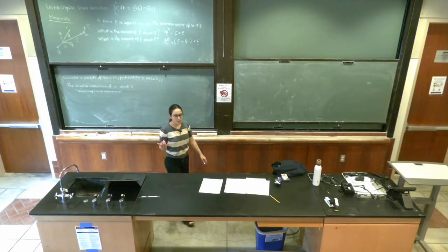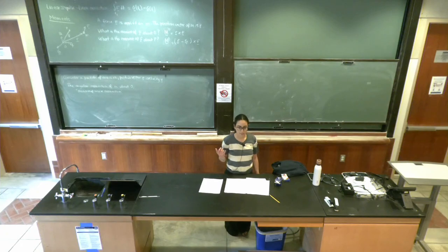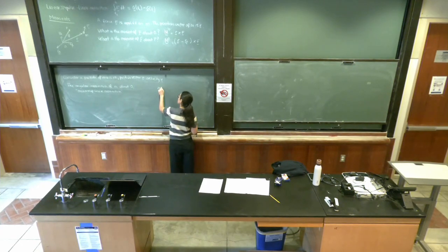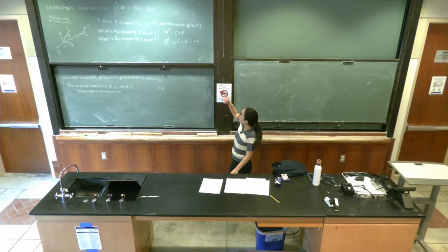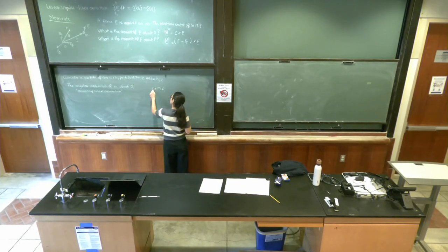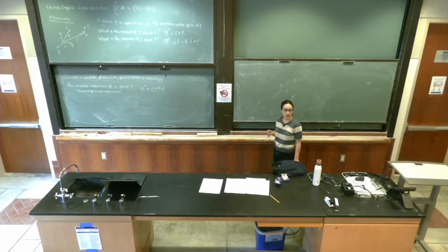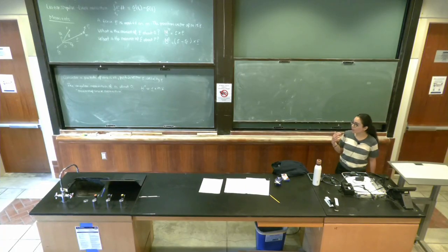What is the linear momentum of a particle m traveling with a velocity v? mv, right? The linear momentum of the particle is mv. And instead of calculating the moment of the force, we calculate the moment of linear momentum, and it's going to be r cross mv. And that's the angular momentum of the particle about O.